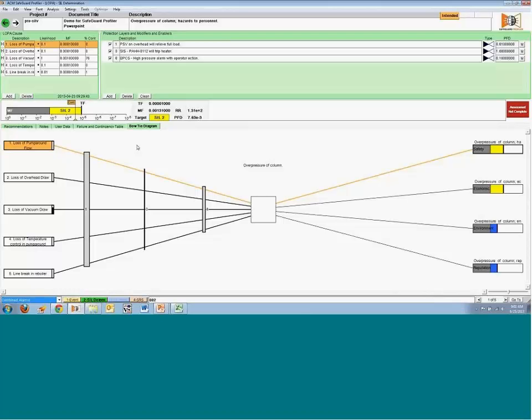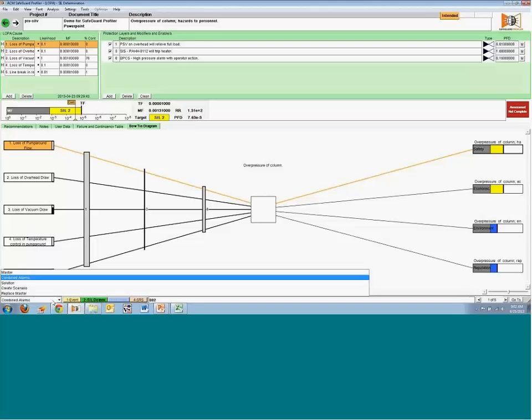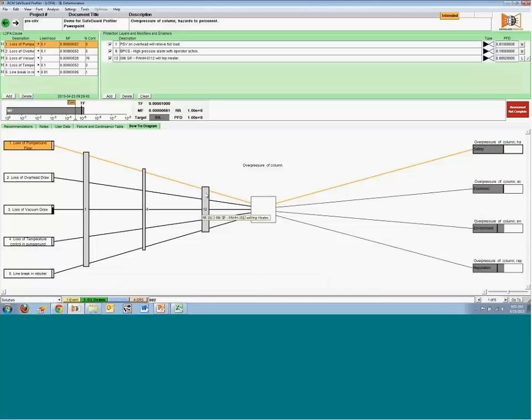The next thing to do is going to be to apply this SIL 2 with that PFD to the SIF, which is number 3 in this one. You can see right now it's got no reliability, so it's thin. But once we apply that exact reliability, this is what our bow tie is going to look like. This is our SIF now, nice and thick. And our LOPA graph has exceeded the tolerable frequency, so we're good. You can see on the right, all scenarios are in a safe state.